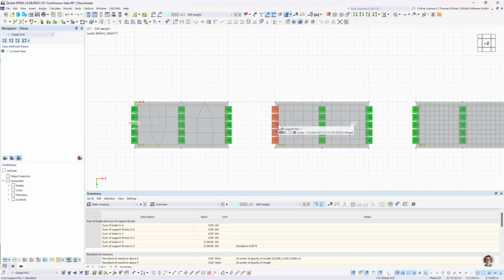You should use 6 elements between 2 supports, or also if you have a line load or a support load, you should also have 6 elements between this line load and the next support or line load. Like everything, if there's a change in the boundary conditions or the force, there should be about 6 elements to the next change.